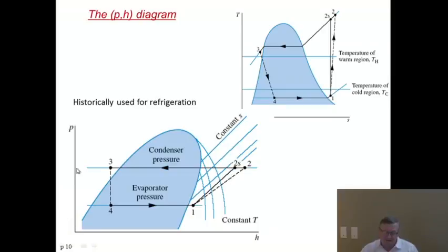The nice thing is that it gives you a direct measurement of pressures, and pressures are very important in selecting refrigerants. So another thing that matters, the isotherms that were horizontals here correspond to these curved things here, whereas the isentropes correspond to these straight things up there. But these are the isotherms.